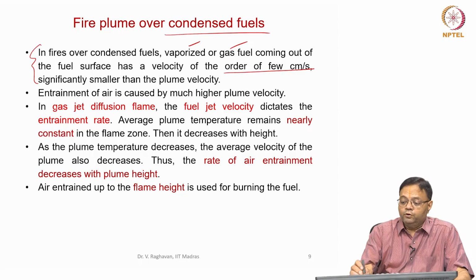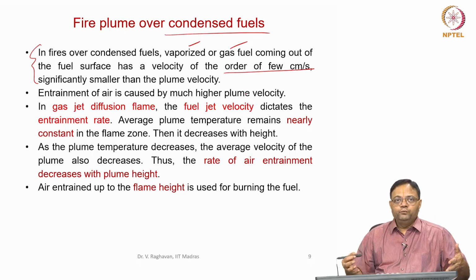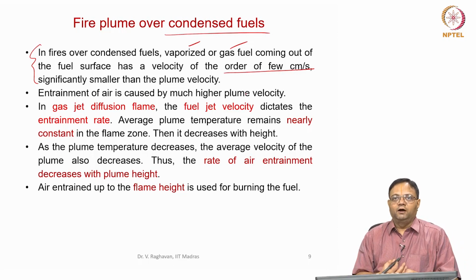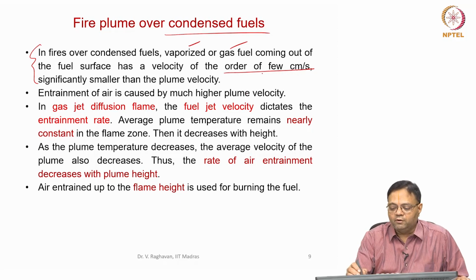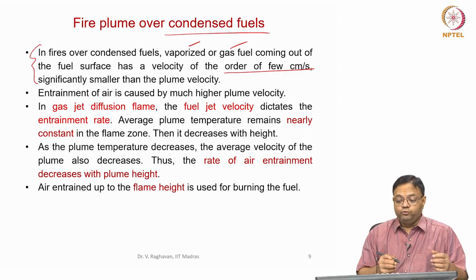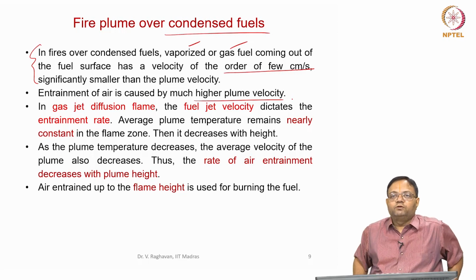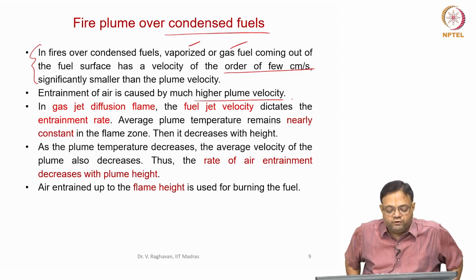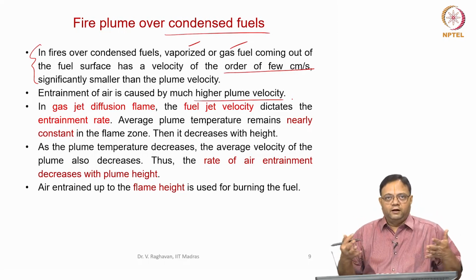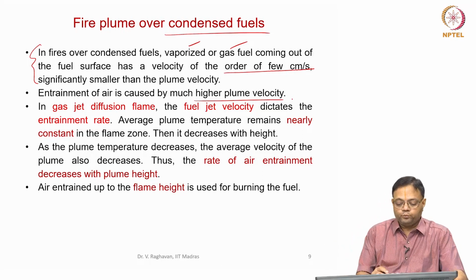And you can see that the entrainment of air from the ambient towards the flame occurs not due to the momentum of the small velocity gases coming out of the interface, but due to the higher plume velocity. Do you understand? The plume velocity is higher, so that causes the drag and it draws in the air from the ambient.